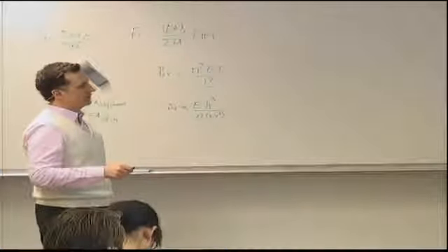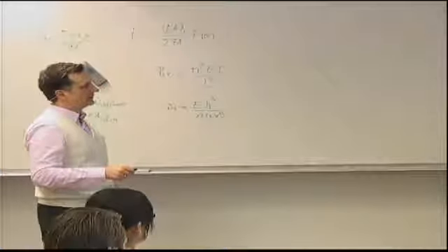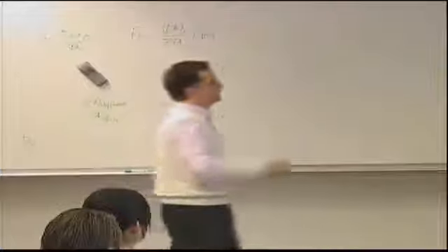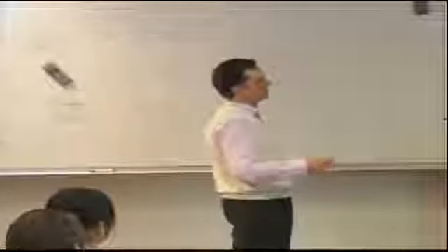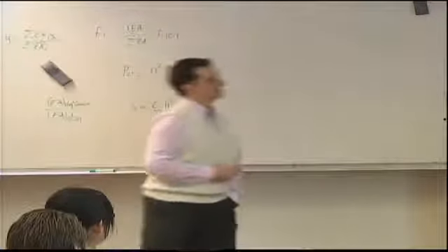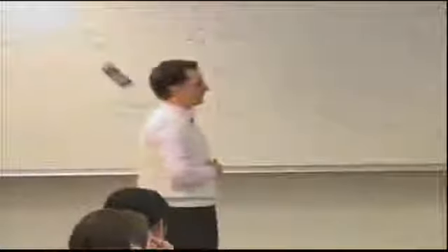The corresponding D11 is a ridiculous difference. It's not even funny how bad the bending stiffness of the second laminate is. And of course the thicknesses, and as you might expect, part of the problem in the difference in D is because this 3-ply flange is very thin.